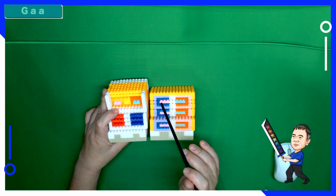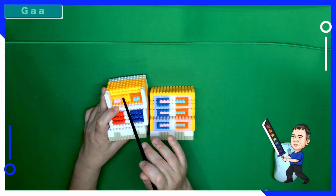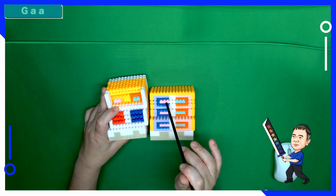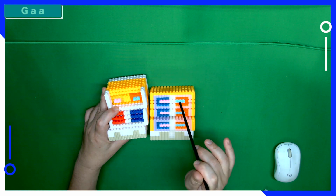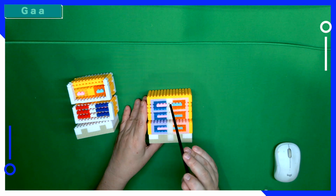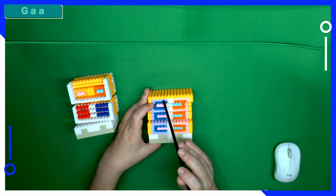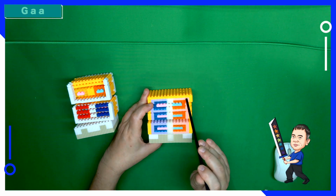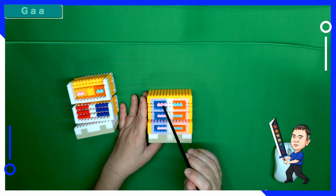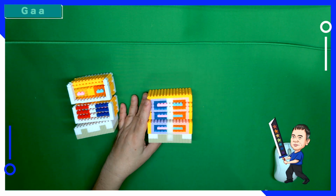But we want to reduce the size between them. So what I do, I use one insulating layer to replace the insulator, gate, insulator, three layers. Then I can shrink the distance between the P channel and the N channel. Another thing is, since I separated the N channel and P channel, I can use different metal material. Note here, the purple material and the pink material are different metals with different work functions. Different work functions allow the gate to control the channel better for the different P channel and N channel.